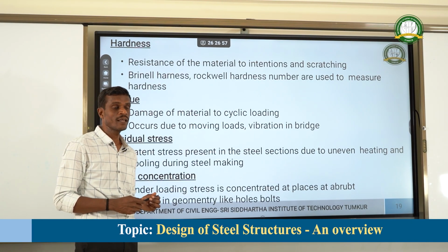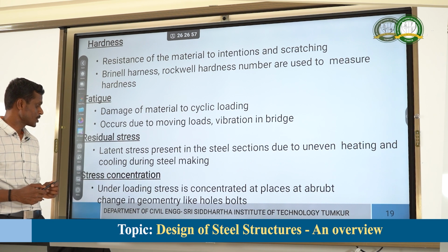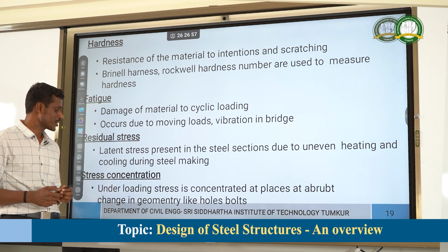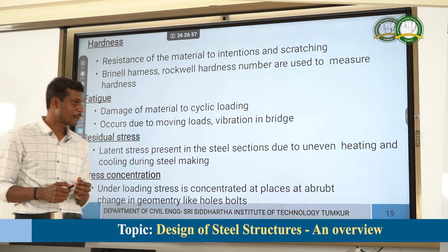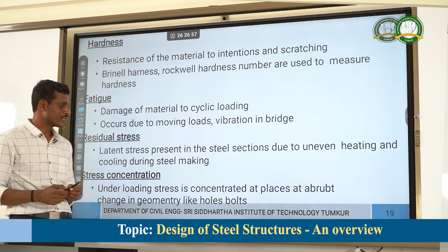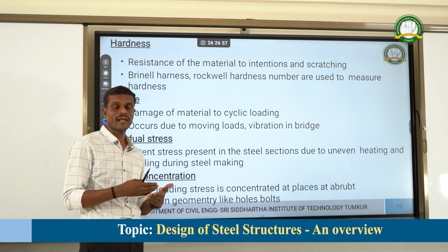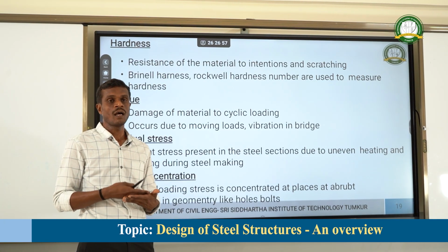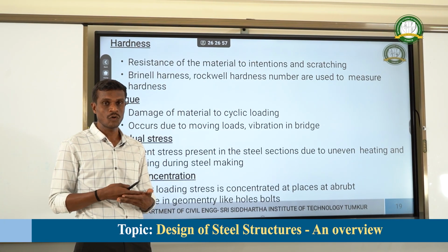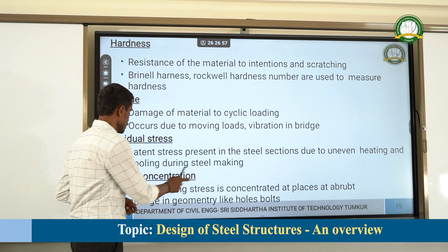This is one of the defects. And stress concentration: under loading, stress is concentrated at places of abrupt change in geometry like holes and bolts. We connect steel structures through connections, it might be bolts or welding. If we drill holes, they may undergo stress concentration.